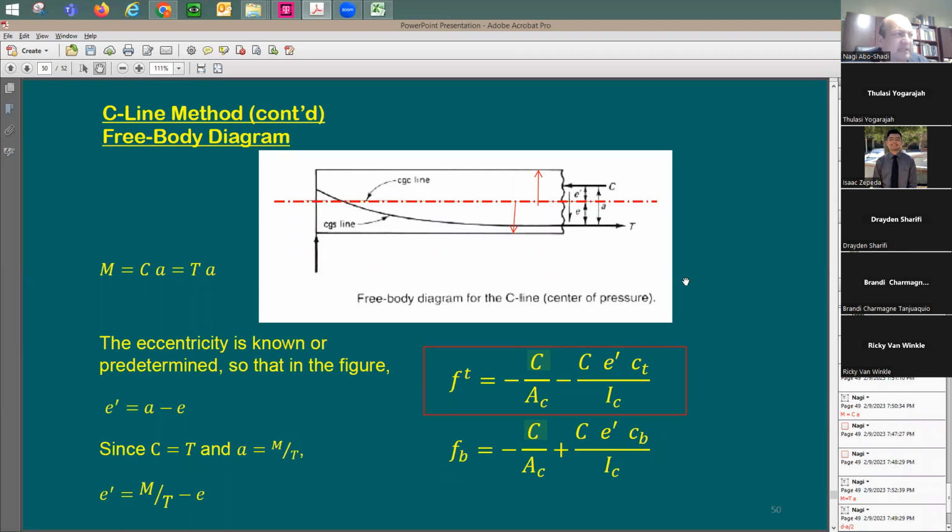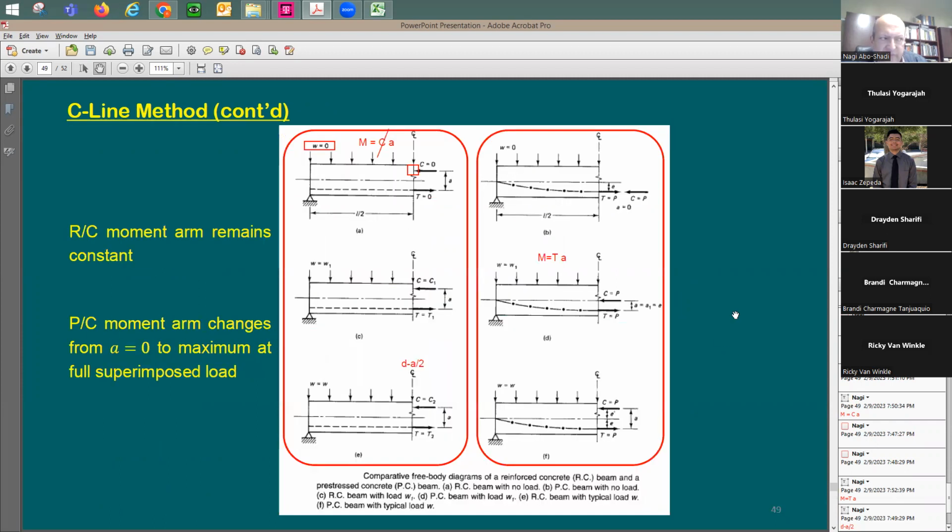This is fine, but this is not actually the best form of equation. But this equation explains something very critical and very important. This amount of tension force grown up in the steel, and also the compression force. You add more loading, if you have some incremental load in conventional concrete, what's happening? This force here grows as the load increases. So this compression force and tension force is just going to be going up. This is the nature of it.